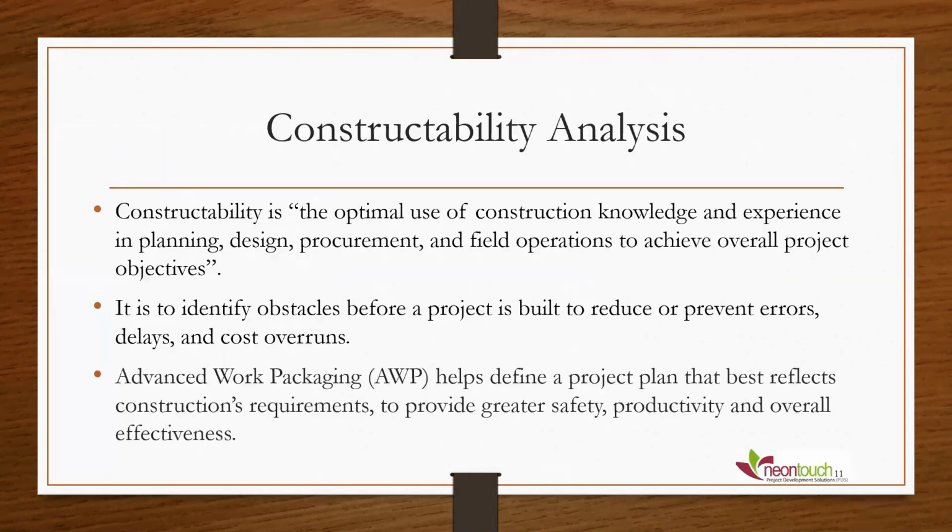Talking about constructability, which is very key, is the optimal use of construction knowledge and expertise to influence planning, design, procurement, and field operations to enable you to achieve your project objectives. It is to identify obstacles to a project before you even get into the field. You want to see those problems on paper and solve them before your project gets into the field at all, so that you can minimize delays and cost overruns.